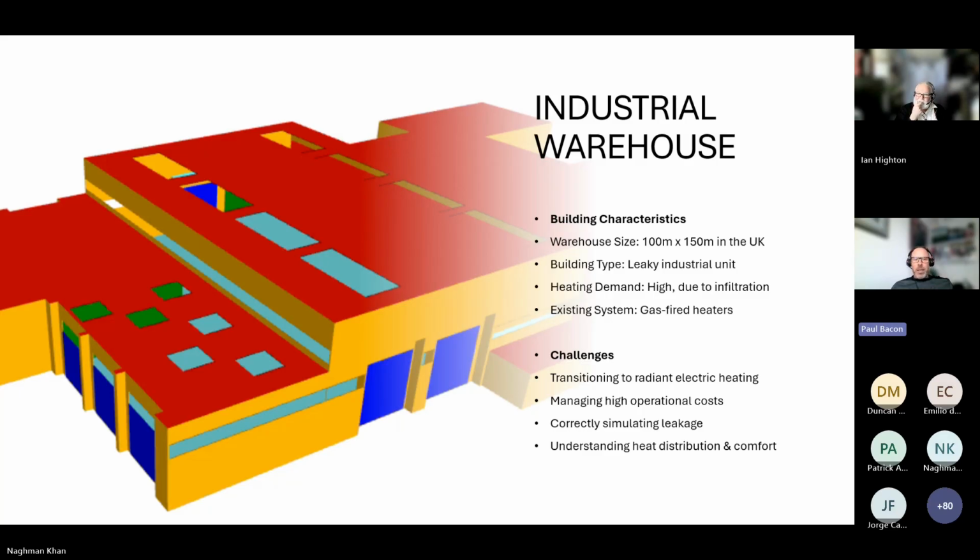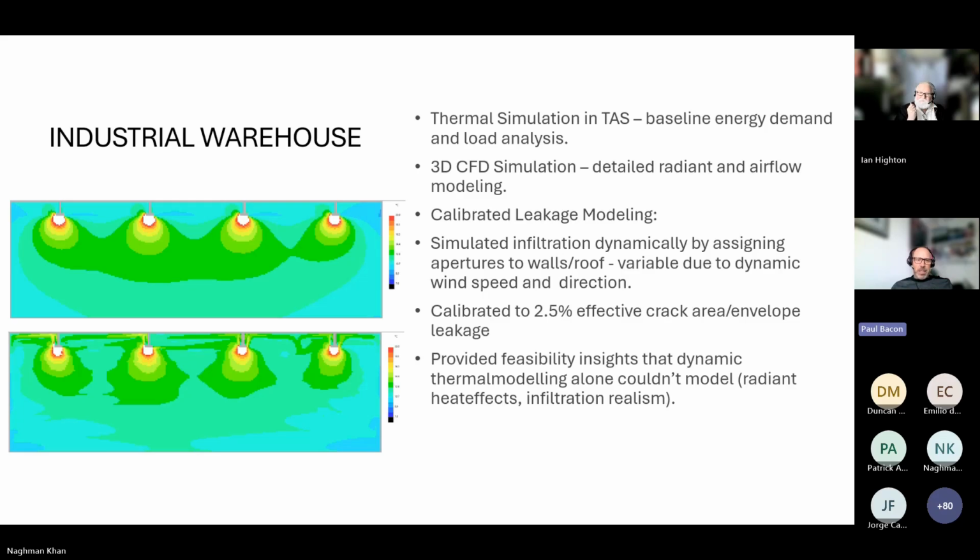After this, they wanted to work out how they could reduce their energy, because it was predominantly an air system in there. So we came up with some scenarios of scheduling doors first of all, because most of the heat was being lost through the doors, especially being an air system. We looked at different set points for the temperatures, and we looked at radiant systems, as you can see here.